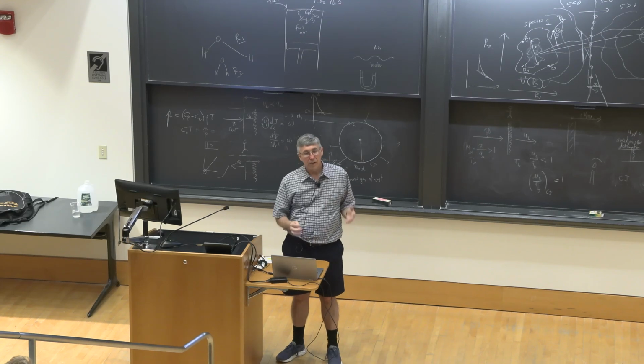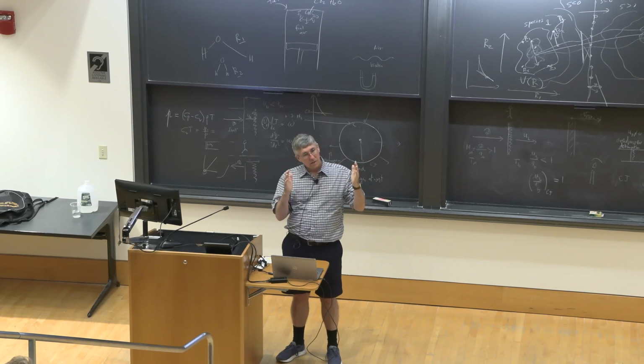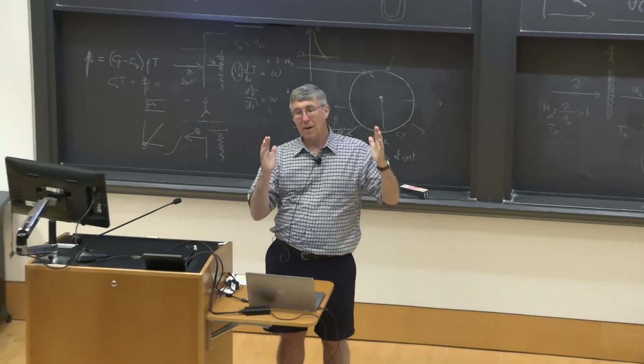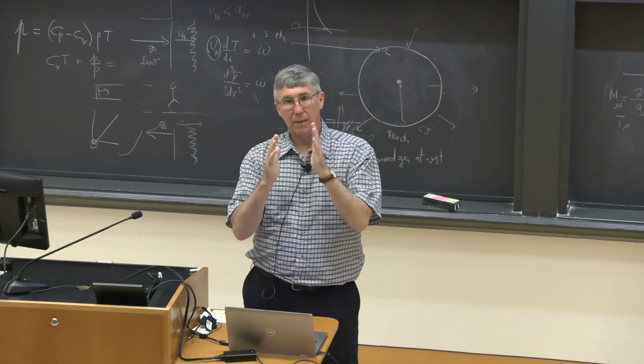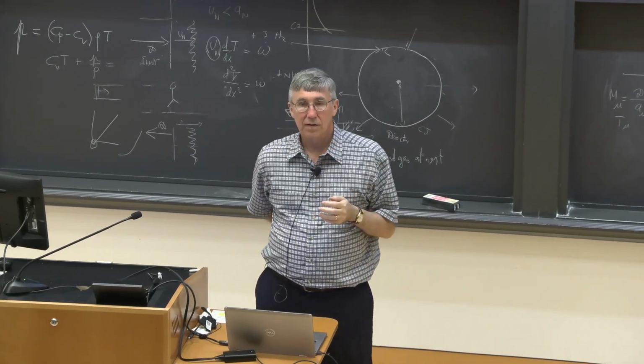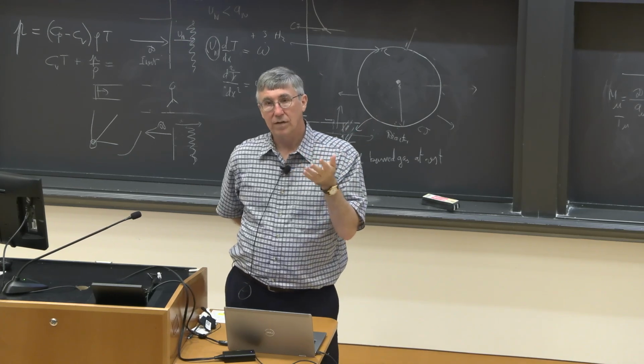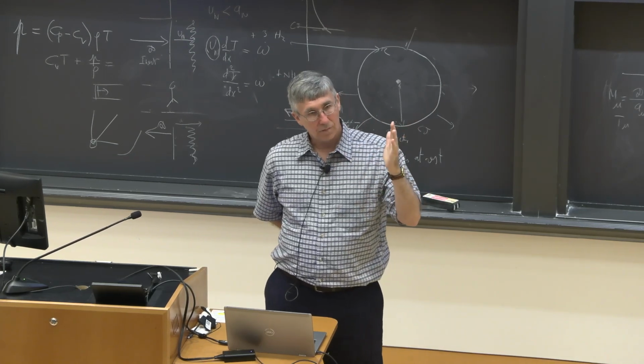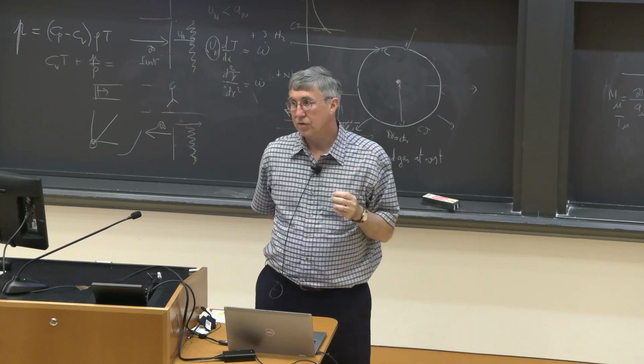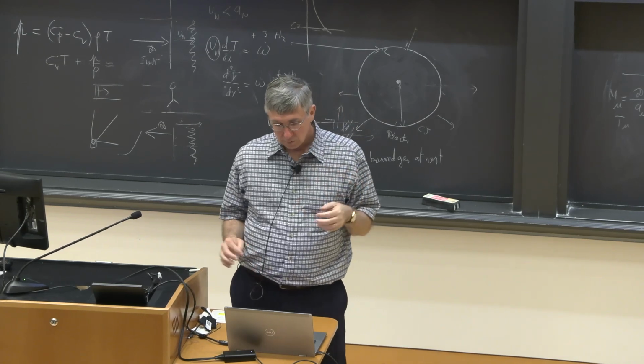There are some people that have a different thing where it's kind of like a mechanical piston, a magnetic piston thing that jams up and makes the shock. And so that way you can make the shock waves more often because you don't actually break the diaphragm. You just have a piston motion that forces the shock wave. And so that's an alternative way.